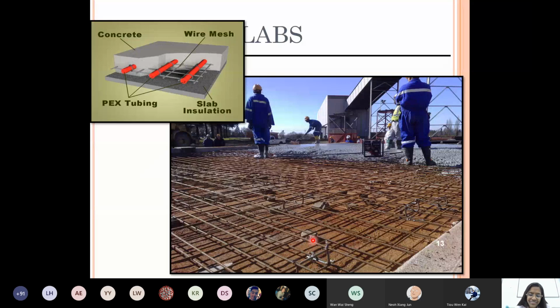I will show you tomorrow. Sometimes it is that. What is this one? Cover. This is called cover, acting as a cover for your reinforcement. Listen, if the cover is not there, the steel will be sticking to the bottom. The bottommost one is the formwork. The brown one is the formwork, right? The formwork and the steel reinforcement should be separated by the cover like this, 5 to 10 centimeter they maintain. It is equivalent to the height of the cover.